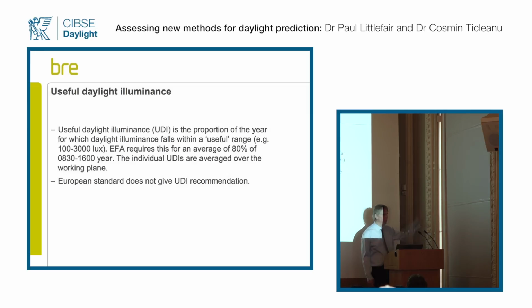So if you brought the blinds down, you've got to calculate the whole room like that, and so obviously you might get a lower UDI at the back of the room. Perimeter triggers the blinds coming down, and therefore obscures the whole of the room. Yeah, well, it would. I think that's fair, isn't it? Because that's what would happen in practice.